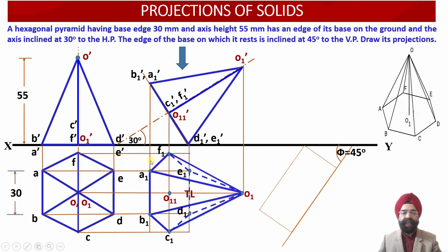Now we can check. Here we have this rectangular box which is inscribing the hexagonal base of the solid. Now different points are required to be marked. We can see this is the longer edge, so this longer edge we have drawn. This is the shorter edge of the rectangular construction, so this has been marked over here.